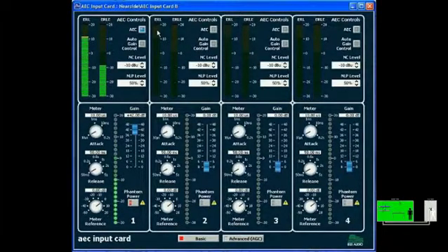Traditionally, the NLP level must be carefully tweaked until achieving a delicate balance between best double talk performance at 0% and best elimination of indirect room-colored echo at 100%. The specific NLP level at which these two performance factors are optimized is often referred to as the sweet spot. Fortunately for installers,